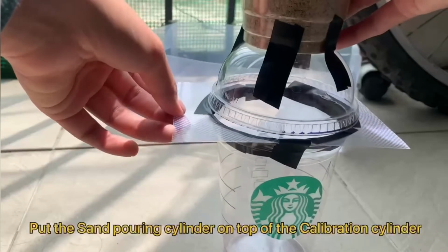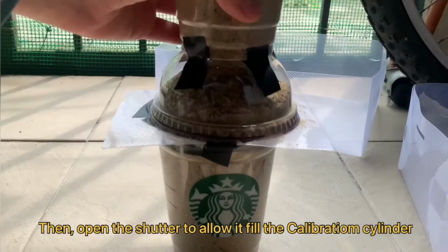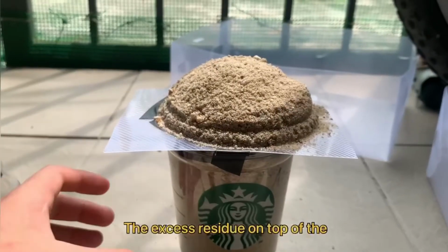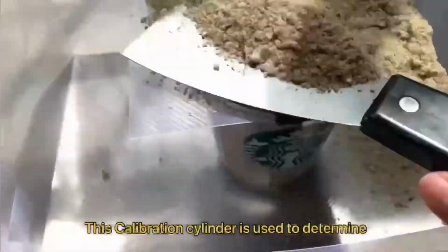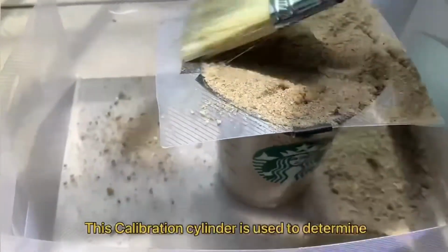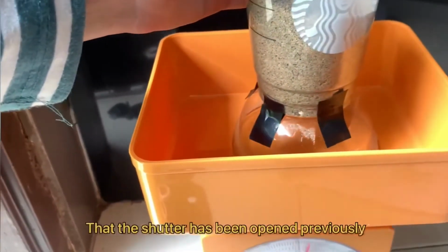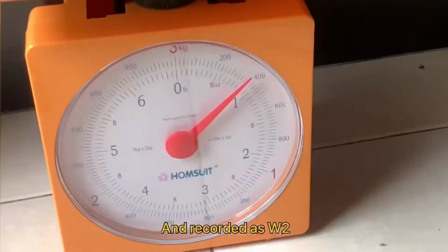And then put the sand pouring cylinder on top of the calibration cylinder. Then open the shutter to allow it to fill the calibration cylinder. The excess residue on top of the calibration cylinder is known as heap of sand. This calibration cylinder is used to determine the density of the sand. Weigh the mass of the sand pouring cylinder that the shutter has been opened previously and record it as W2.